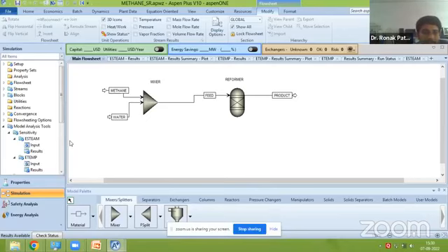So we can add them as pseudo components. Pseudo components are there, so by means of pseudo components, we can add them. But for them, we require certain additional things. For example, we require the data on how the density is going to change, how the viscosity is going to change with respect to temperature and pressure.